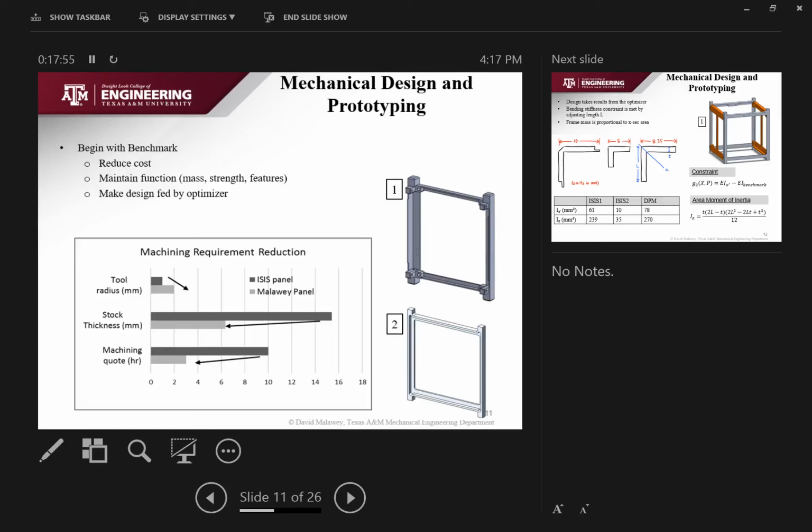And then secondly, I reduced the thickness of the raw stock needed to make the part. So if you're just considering making this part and starting with a raw material or a raw plate, I reduced these bosses so that your thickness is reduced by 50% at least, and then those bosses carried some functionality that had to be replaced. For this, it was for mating to the other components, and I had to add in holes in order for my part to still be functional.